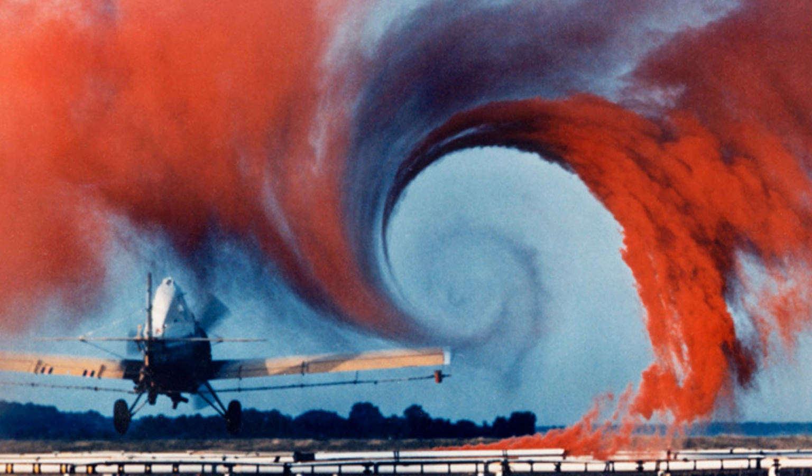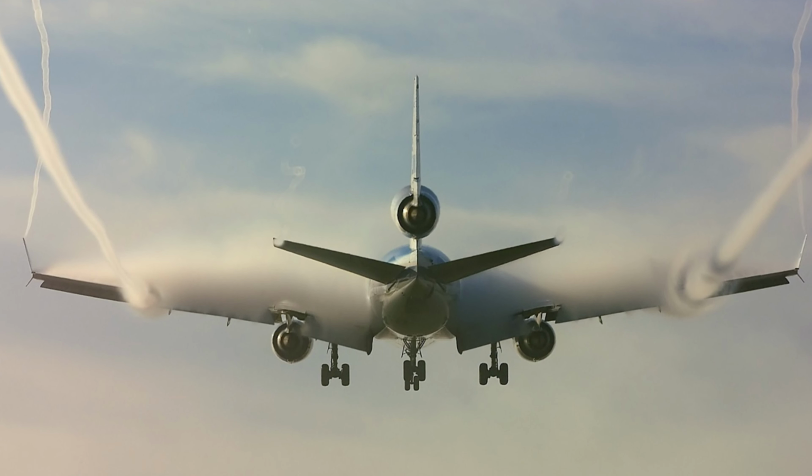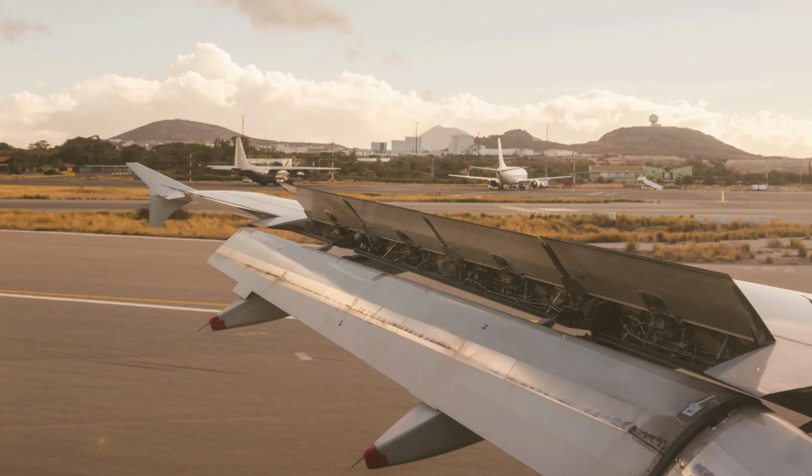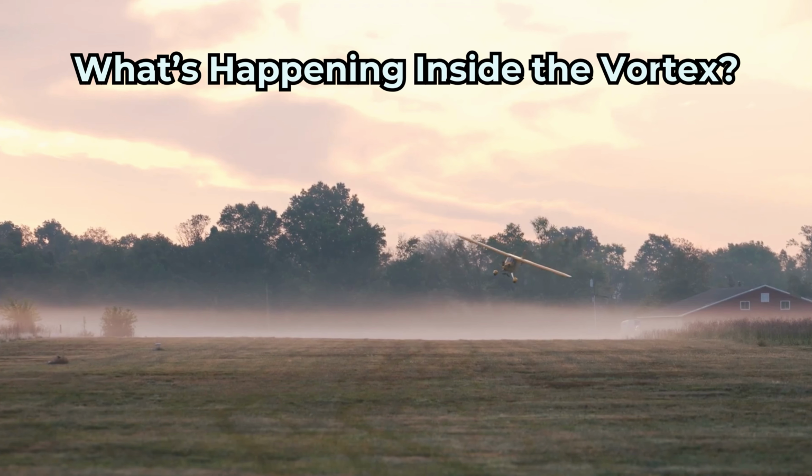The best way to see the shape of the vortices is if you see the aircraft pass through some smoke or some cloud. Wingtip vortices are a byproduct of lift. Once the wing stops producing lift, the vortices dissipate instantly. If you see an aircraft landing on a cold day when the vortices are visible, you'll see that they disappear the moment the aircraft raises the wing spoilers. Wing spoilers drastically reduce the lift generated by the wing. As soon as the spoilers rise, the wing stops generating enough lift to support the weight of the aircraft, and the vortices cease.